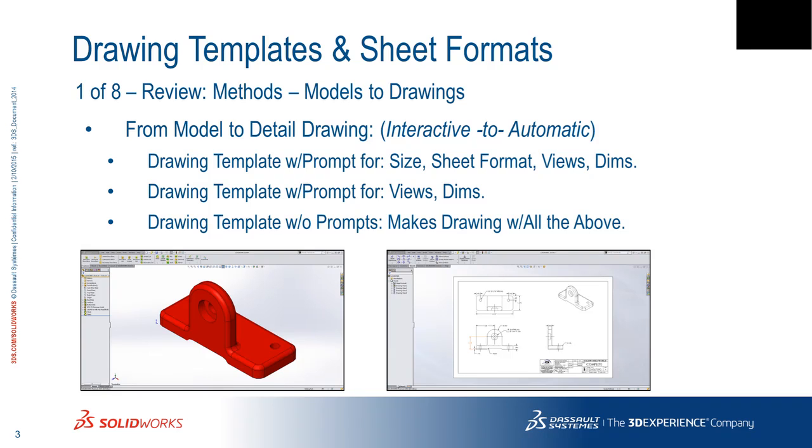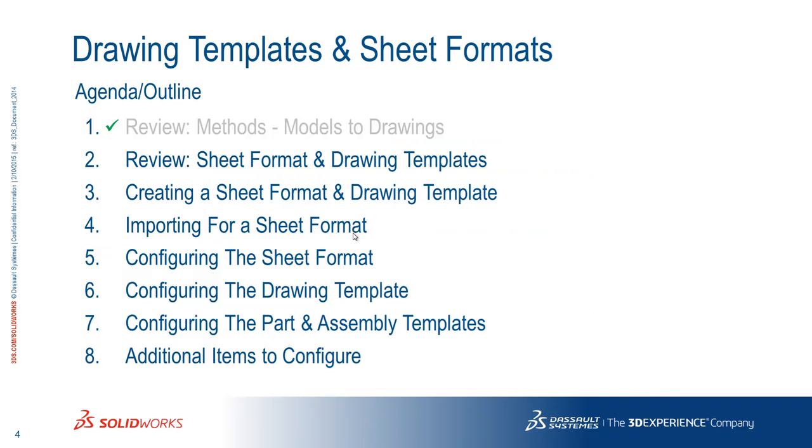And that's really what this presentation is about: how to get to that point instead of having to use the default one that they give you, where it asks you for the size every time. You have to pick the sheet format every time and drag your views out every time. Because to me, that seems a little repetitive.